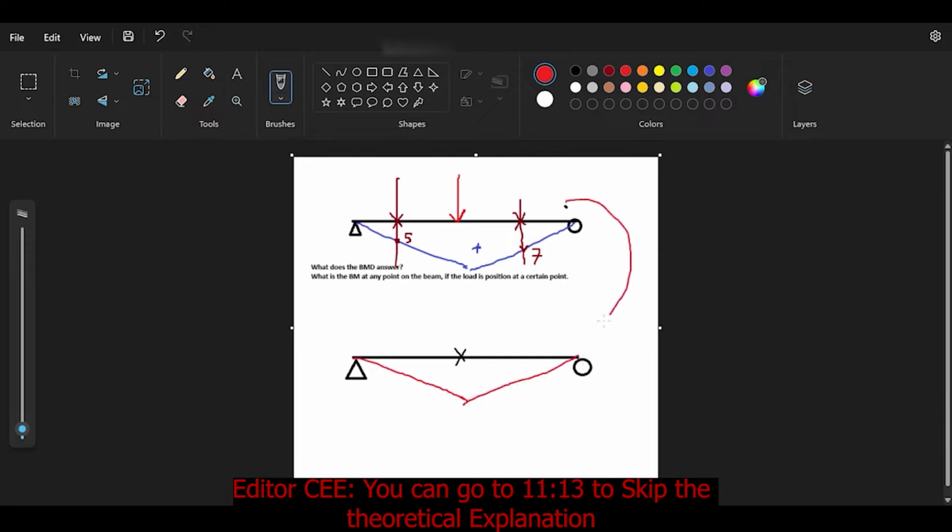Of course, I'm going to use the design moments, so I'm going to bend it like this. Okay, now they look similar, it seems, because it's a simply supported beam, but there is a major difference here. The major difference is, first of all, we drew the influence line without knowing the force. We don't know what the force value is. The only thing we know is the force position. Okay, that's the first thing. Influence line is using a unit force to be drawn.